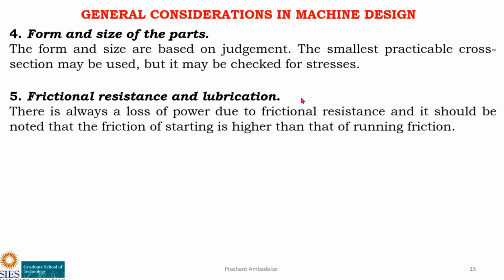If the part that needs lubrication is slightly inside, then the oil hole should be properly directed so that there should not be any frictional resistance, or the frictional resistance should be as minimum as possible.